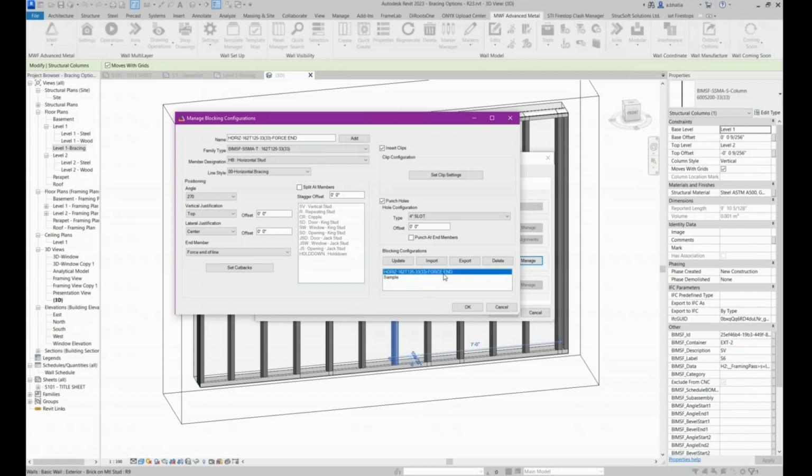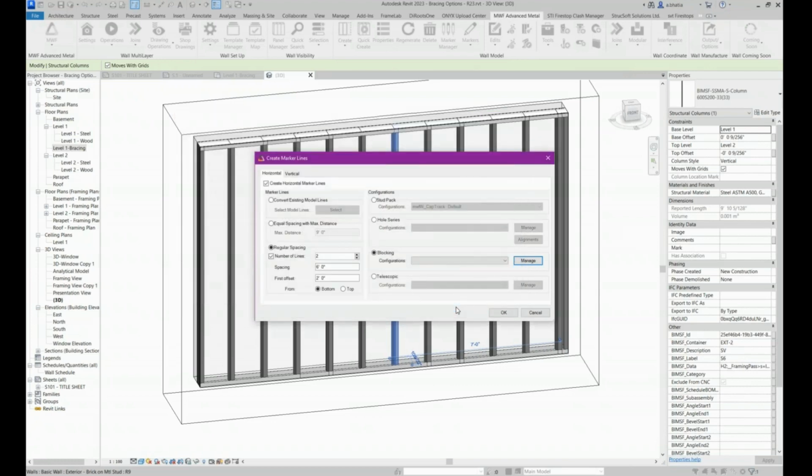Okay. So I'm going to create multiples of this because I just want to show you what these other options do. So if I come here, force end, and then I'm going to change this to stop at nearest. So I'm going to just change this to be called stop near and hit add. All the other settings are the same. Nothing changes except for this. And we're going to extend to closest. So we'll just call this extend, and we'll hit add. Okay. All of them are using the exact same settings, just that value is different. So we'll go ahead and hit OK.